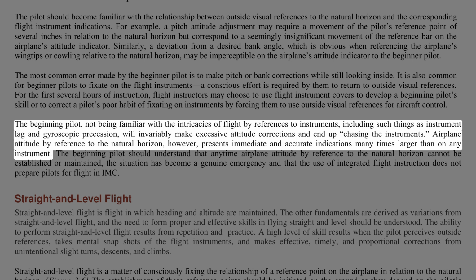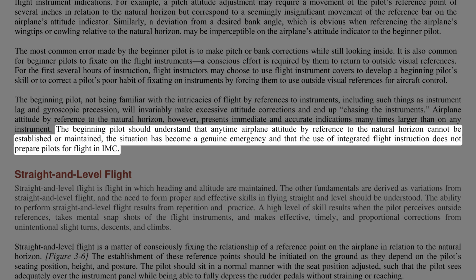The beginning pilot, not being familiar with the intricacies of flight by references to instruments, including such things as instrument lag and gyroscopic precession, will invariably make excessive attitude corrections and end up chasing the instruments. Airplane attitude by reference to the natural horizon, however, presents immediate and accurate indications many times larger than on any instrument. The beginning pilot should understand that anytime airplane attitude by reference to the natural horizon cannot be established or maintained, the situation has become a genuine emergency, and that the use of integrated flight instruction does not prepare pilots for flight in IMC.